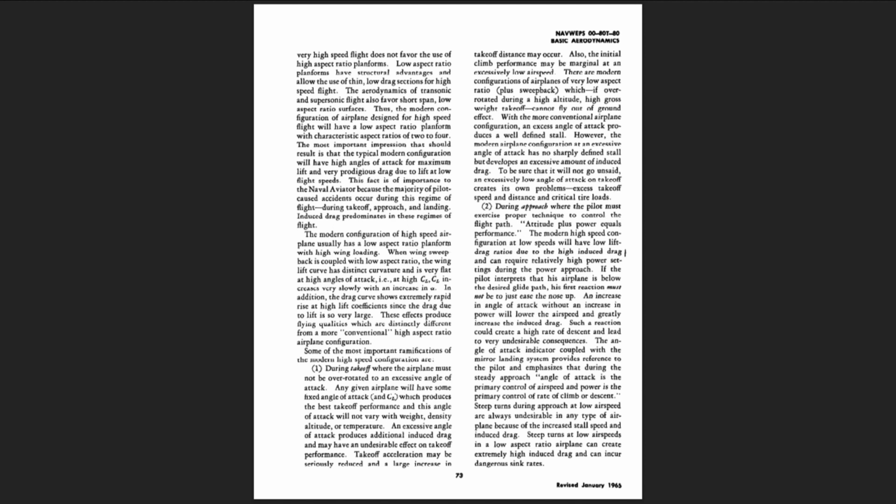The angle of attack indicator coupled with the mirror landing system provides reference to the pilot and emphasizes that during the steady approach, angle of attack is the primary control of airspeed and power is the primary control of rate of climb or descent. Steep turns during approach at low airspeed are always undesirable in any type of airplane because of the increased stall speed and induced drag. Steep turns at low airspeeds in a low aspect ratio airplane can create extremely high induced drag and can incur dangerous sink rates.